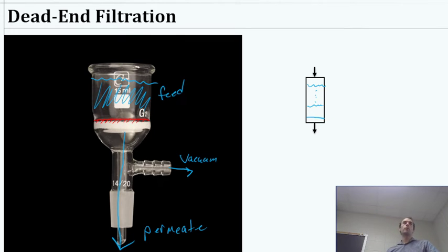So in laboratory things, maybe that's actually really helpful if you're trying to, let's say, concentrate some bacteria or something to study. Maybe you do want to filter some of the water through, concentrate your analyte, and then do whatever measurements or something. And the permeate itself is what's going to waste. So even though we don't have a retentate flow or a concentrate flow, we can take a concentrate if we don't filter everything.